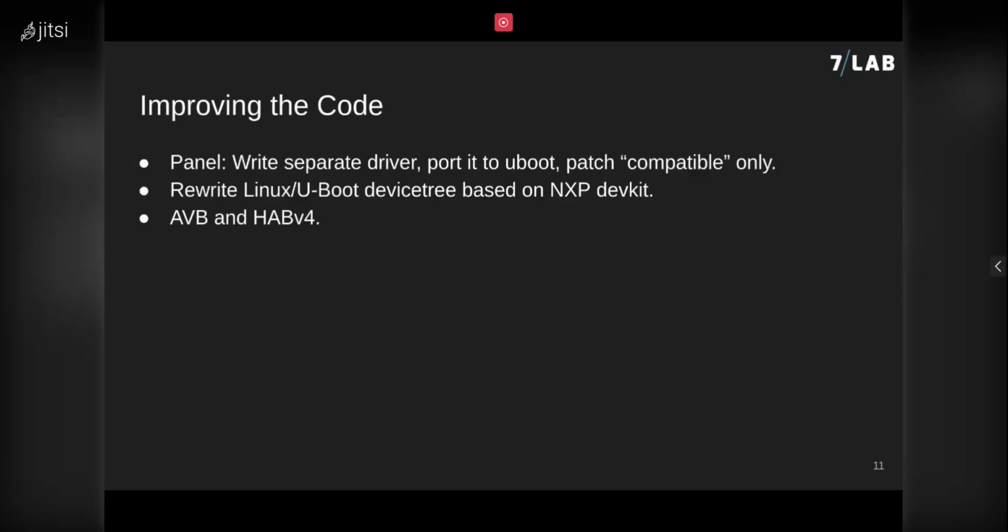And this actually blows fuses in the hardware. And of course, I initially blew the fuses in the wrong order. So maybe important learning here: enable RPMB before you enable secure boot, because if you do it the other way around, then you can't enable secure boot anymore due to the way they derive the keys. And yeah, I had to get a new device to continue my work. So more reading in preparation is always a good idea before actually blowing fuses to enable secure boot.